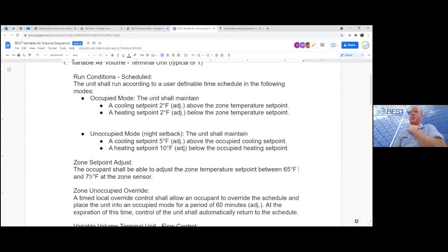This is going to be one of those points when you're going to utilize your translator type tables, that temp table converter from your raw resistance value to make these temperatures. I will tell you that most of the potentiometers that we use in our field on these thermostats are nothing close to linear. So do not assume just because you have a 10,000 ohm sensor that you can do a top and a bottom and range and be good between those. The middle is usually pretty close to the middle of their range, but as soon as you get outside of those 3 points, things are very nonlinear.